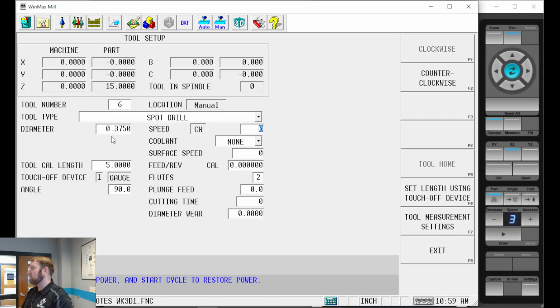Most of the drilling we do, or spot drilling we do, is going to be done with this. Towards the end, we're going to use that center drill a couple times, only because I want you to learn the center drill formula that I'm going to give you. Your center drill's got the point on it, which, for numbered center drills, is a set length, and I've got a chart that I'll give you. Then there's a formula to calculate how deep you need a center drill to leave the right size chamfer at the top of your hole in a mathematical way, compared to what we do out there, which is